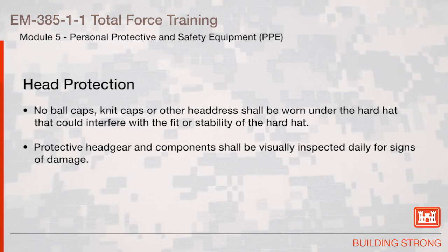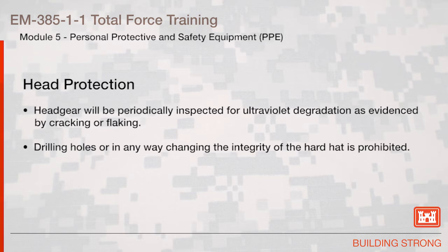Protective headgear and components shall be visually inspected daily for signs of damage. Headgear will be periodically inspected for ultraviolet degradation as evidenced by cracking or flaking. Drilling holes or in any way changing the integrity of the hard hat is prohibited.